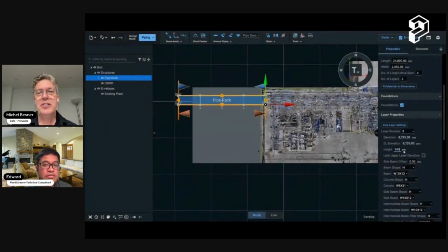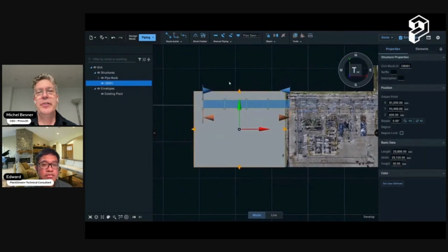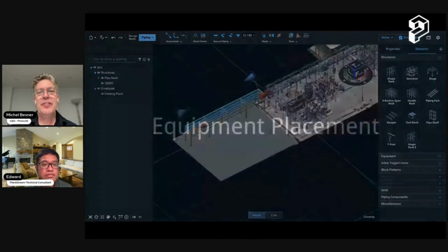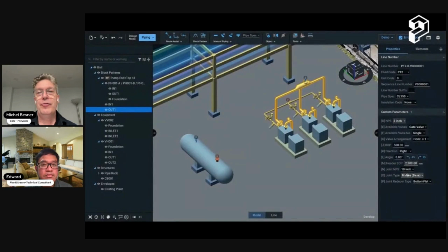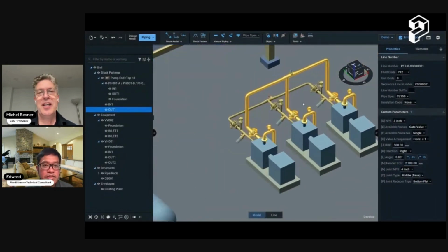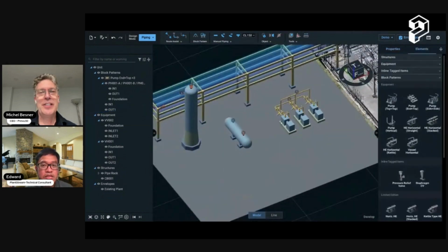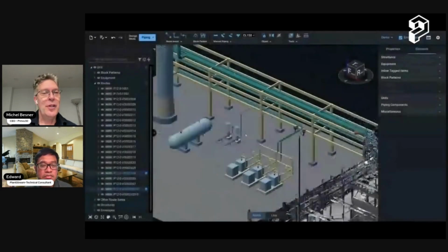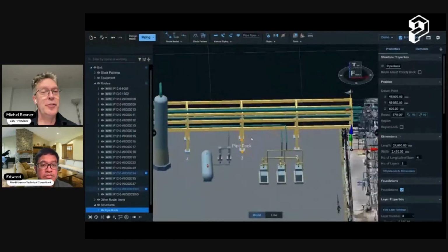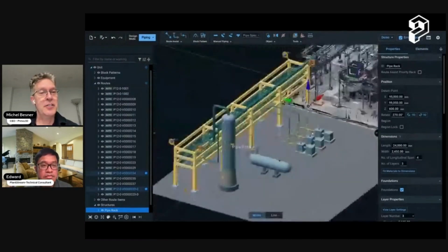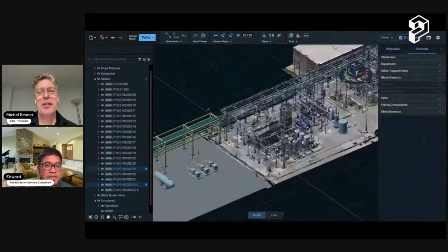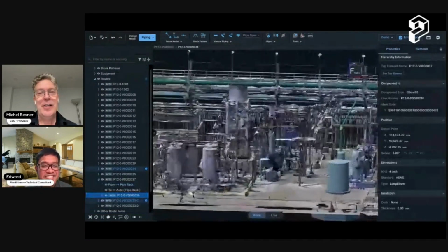Because if you do things in a 100% CAD-only environment, you might not have the exact version of the truth of the site. And so having the as-built scan, there's no way around it. If there is specific piping or other elements that might not show up in your CAD design, like there's obviously things that the CAD designers might not model, including some extra beams or structure in the environment, on the CAD model it looks all perfect.